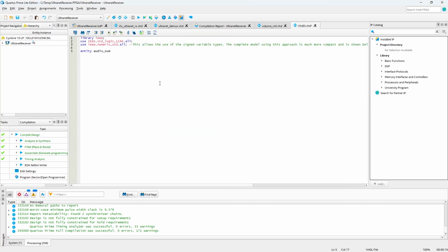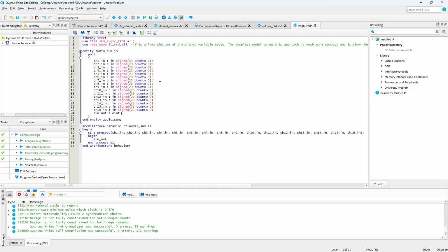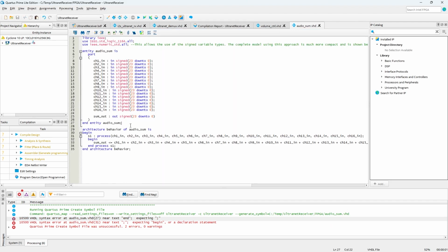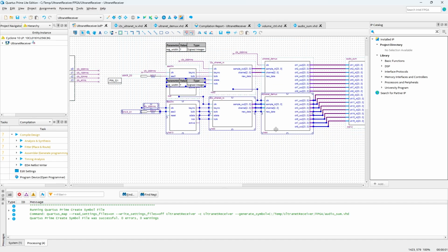Now we have almost all the functions of a simple audio mixer. The only thing missing is the sum of the individual channels and the main section. The sum of the 32 audio samples, 16 for left and 16 for the right, is exactly that, a simple addition of the individual signals. The only restriction here is that we can easily slip into a signal clipping if the signals to be summed are at quite high levels. This could be solved by signal processing with floating or fixed point signal, but this is again more complex in the FPGA. After the summing block, we add another multiplication to realize the main fader section, and the resulting output signals are already the audio samples that we can send to the SPDIF output.